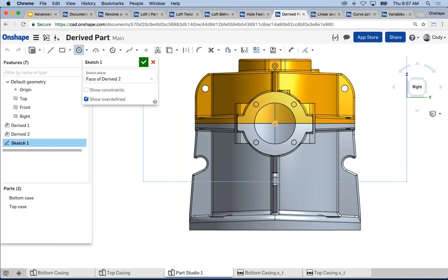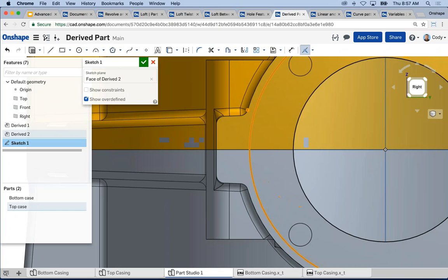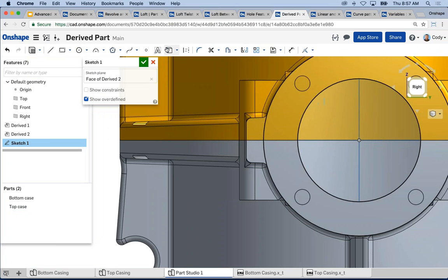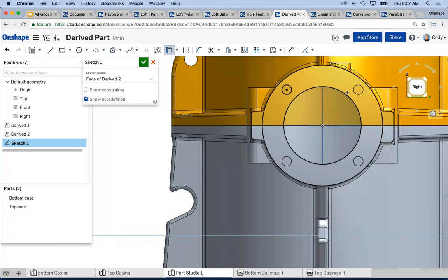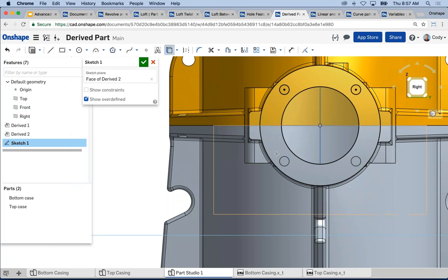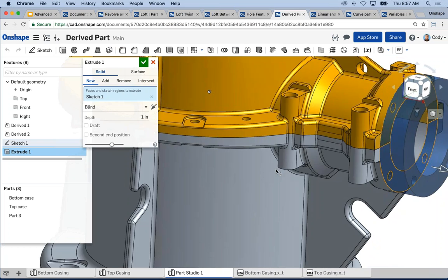Right? So now I can start sketching my geometry. Let's say that I wanted to make something like a simple gasket that attaches to these. Right? It's easy for me to constrain relative to the geometry. Even convert edges. Right? I can grab edges of the parasolid, convert them, and take this and extrude it and create that simple flange.